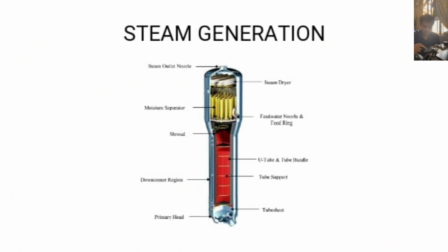As a forced circulation boiler, the narrow tube construction without any large diameter drum or tank means that they are safe from the effect of explosion, even if worked at high pressures. The pump flow rate is adjustable according to the quantity of steam required at the time.